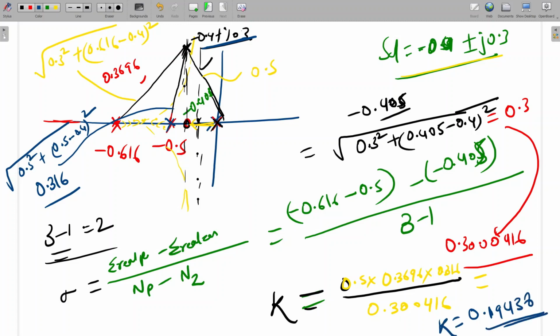So this is our K value to achieve this response. This kind of desired pole we need. So for this pole, is it clear to all up to now? So see here, when a zero was there, that zero will come in the denominator. If two zeros will be there, distance from both the zeros will be computed till the desired point. And both will be multiplied in the denominator.